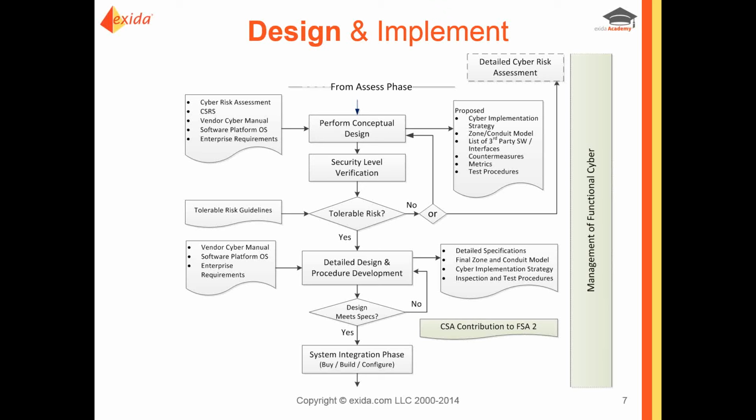This is a little bit more detail of the design portion of the life cycle. Later on, we'll be looking at the implement portion. It goes through performing conceptual design, doing your security level verification, determining whether you've met your tolerable risk criteria of your corporation or not, all your detailed design and procedure development activities, and after that then you go purchase, build, configure.